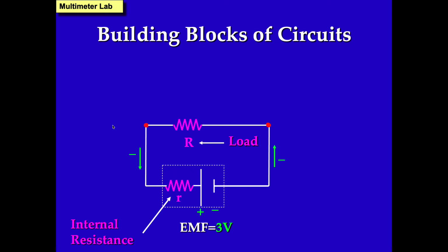And you draw the little R in there. For most of the problems we're going to do, we're going to ignore the internal resistance. In fact, in reality, you're supposed to have a power supply where that little R is as close to 0 as possible. If you're using a battery, that's not the case. When a battery gets older, that R gets bigger.